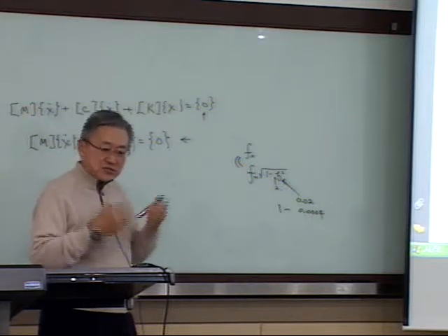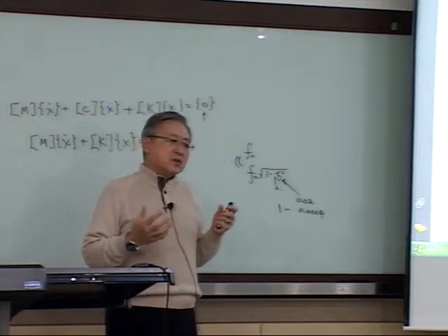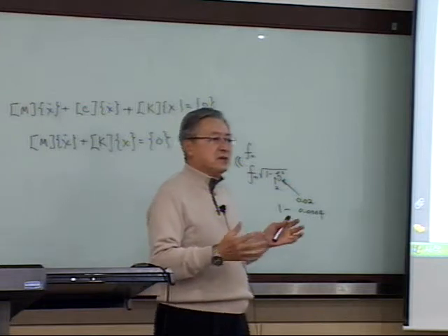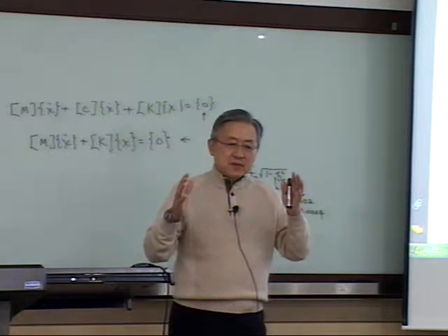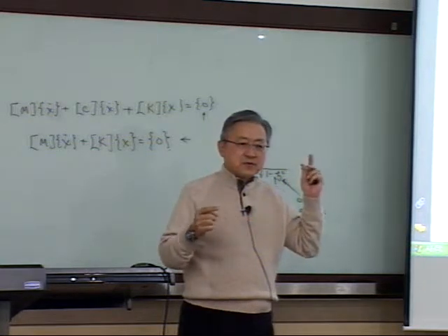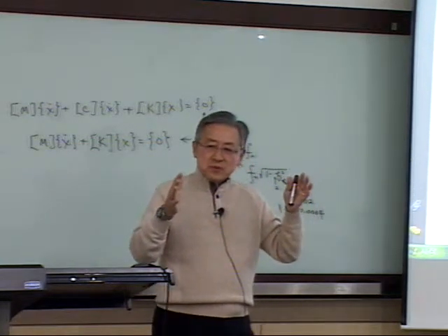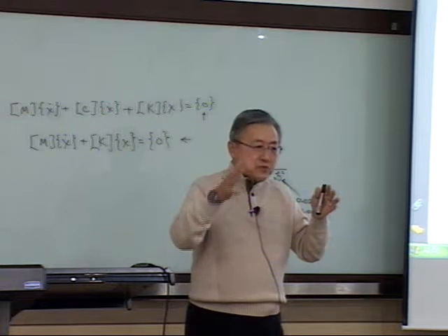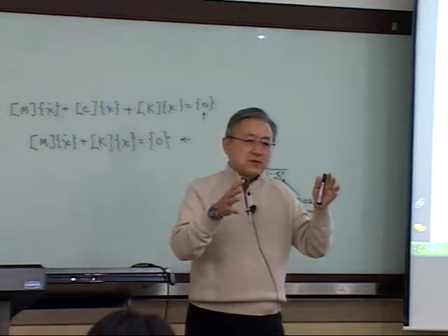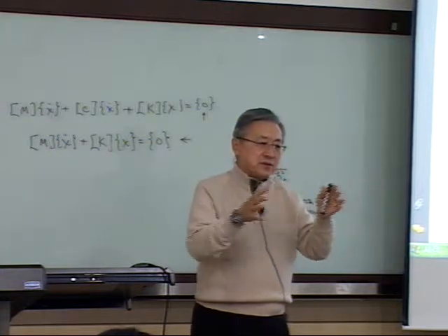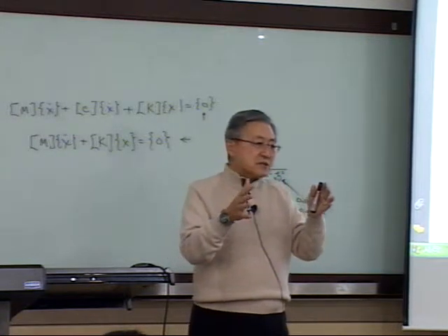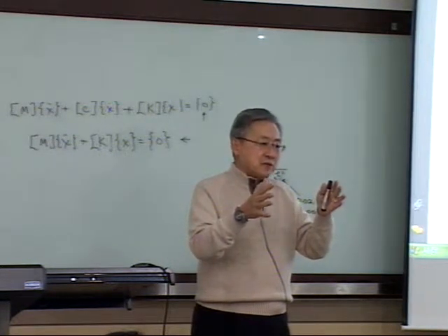Mode shape wise is a shape. Mode shape does not tie down with the dimension. So like a 3 degrees of freedom system, the first mode, intuition first, okay? First mode is usually in phase, acting together. And the second mode is out of phase.